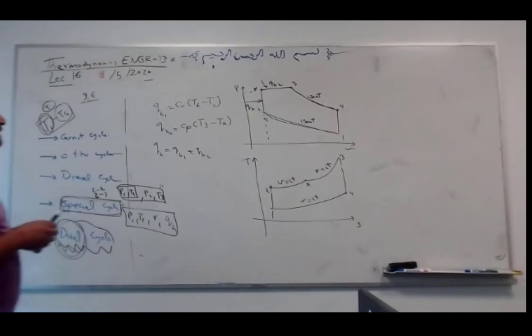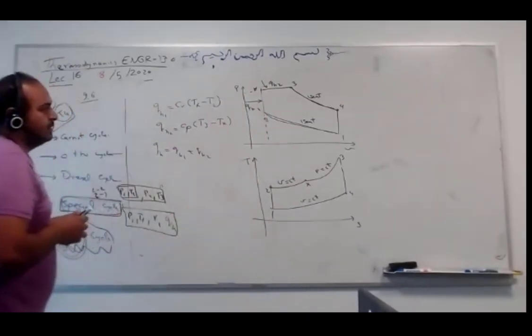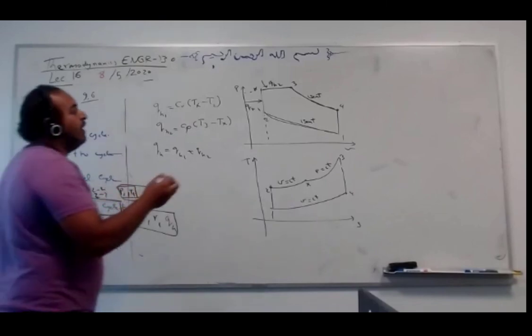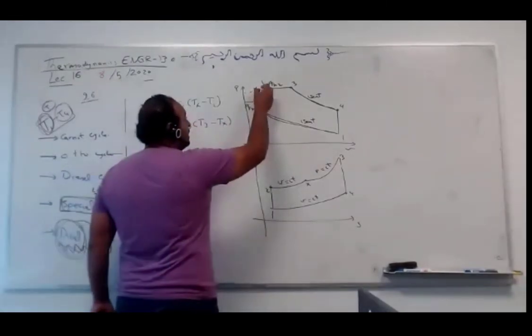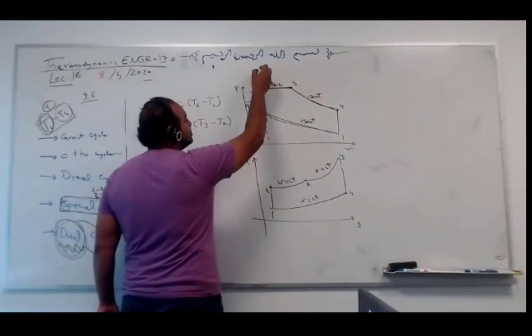If you keep going vertically from 2 to 3, this is huge pressure, too much load on the material. That's why Diesel has some advantage, but Otto has an advantage too. Otto is more efficient if you have material that can be stable at very high pressure and temperature. So we can have high pressure and keep increasing temperature, but the pressure doesn't go too high.